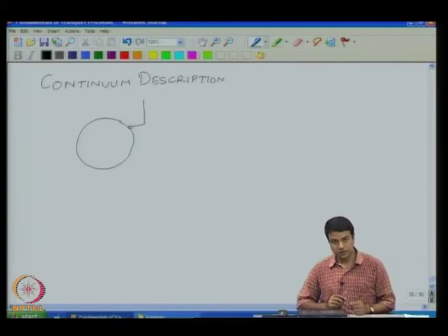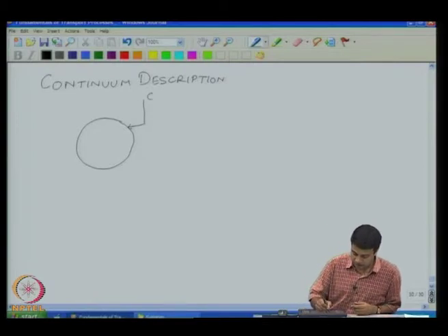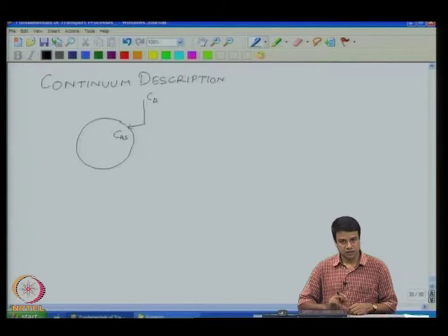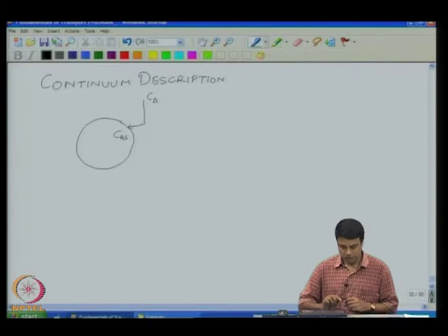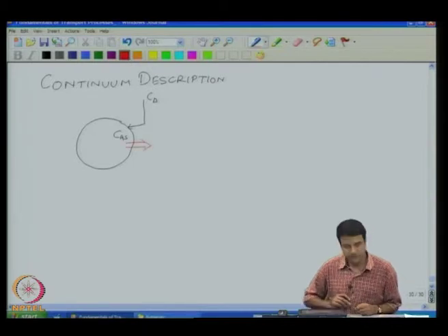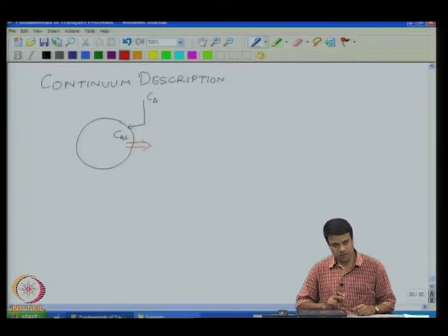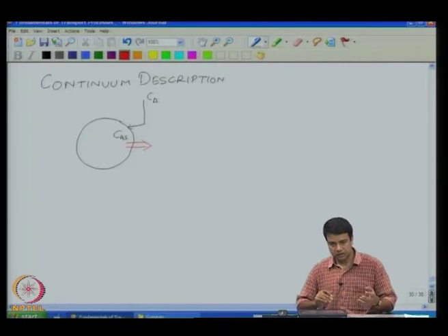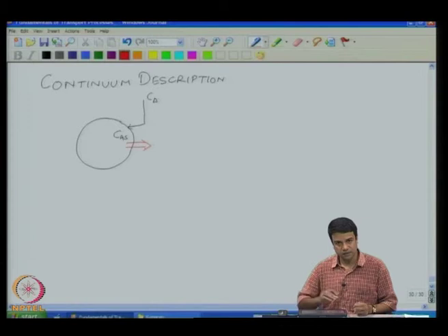Of course, it is going to depend upon the average concentration difference between the bulk concentration and the surface concentration of the material. But the bulk concentration is not a constant. Obviously, as you come closer and closer, the concentration within the fluid has to approach the surface concentration. In a similar manner for the heat transfer problem, the heat that is transferred either into or out of the catalyst surface is going to depend upon the difference in temperature between the surface and the bulk. Of course, the temperature is not going to be a constant throughout the fluid. As you come nearer and nearer to the surface, if the catalyst particle is hotter, the temperature is going to be larger at the surface than in the bulk. So, how do these variations give rise to these fluxes?